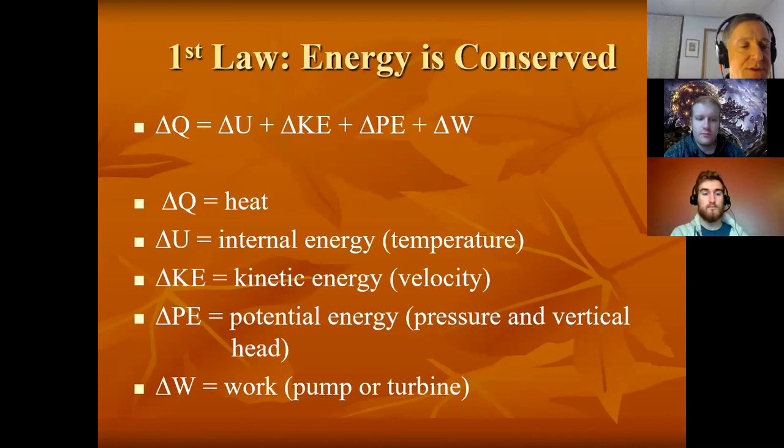Okay, first law again, the change in heat is equal to the change in internal energy plus kinetic energy plus potential energy plus work. And we're excluding nuclear reactions, but this is how this all works. And again, typically what we're doing, if you're dealing with an adiabatic system where you're not adding or taking away heat, you're moving velocity and pressure. That's what we talked about with the Bernoulli equation. We're moving those back and forth.